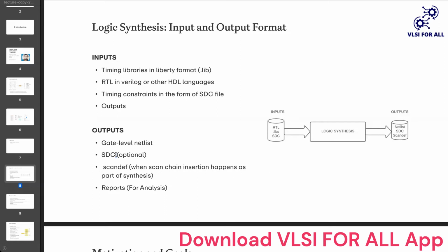Even for the physical implementation, your design still has to adhere to the constraints you used in logical synthesis. That is the reason some people write out the SDC after synthesis as well and use that as an input for the next stage.